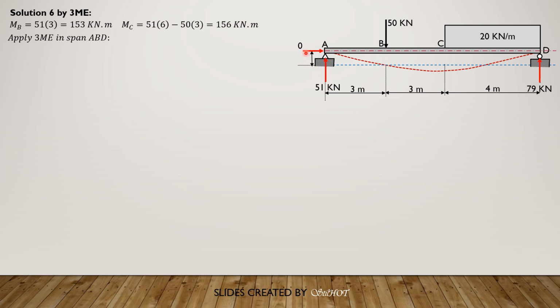Then this is HA supposedly. Then this is the deflection at B. And we have H sub D. So HD and HA are equal to delta B. But delta B is supposedly negative, while HA and HD are positive in this configuration because they are above the horizontal line. A and D are above this horizontal line. Our reference is the horizontal line at B.